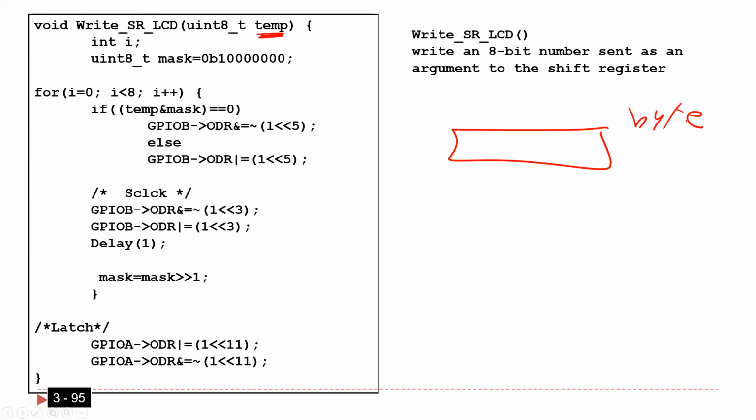And then, as I have just explained, you are going to check bit by bit. How can you check bit by bit? As you see here, and actually that's also what you did in the last lab. I'm going to make something, I'm going to call it a mask. So I'm going to put here 1 0 0 0 0, and then I'm going to do an AND operation. Make sense?